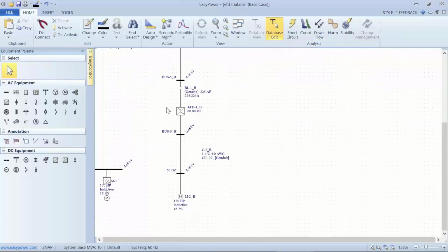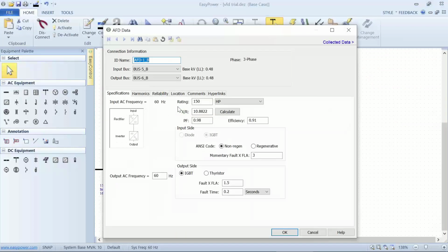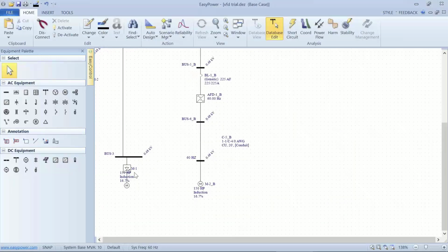and we look at the way we set up the VFD controller, we see that we're driving the output frequency of 60 hertz. We probably should have changed the voltage to 460 or so, but we're showing the power factor being elevated. As long as the efficiency and the power factor are the same, we should have the same results out from the motor that's involved in the VFD setup.